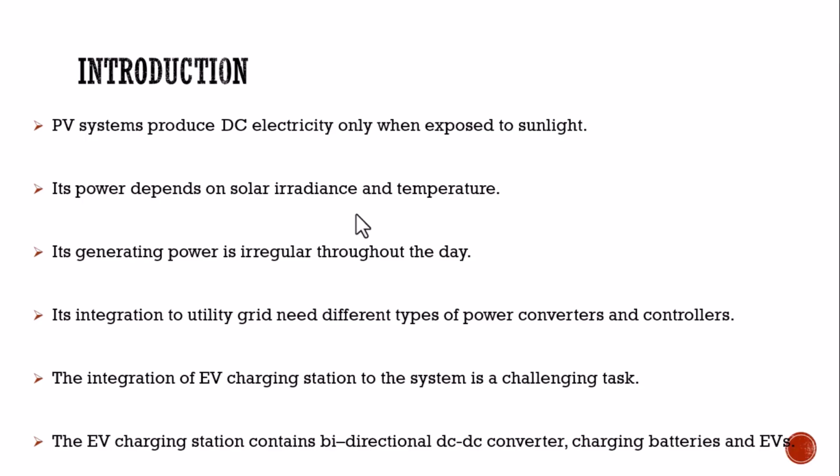Solar irradiance is the principal variable influencing the electrical output of a photovoltaic array. The power generated by a PV panel depends on incident irradiance, cell temperature, and module characteristics. As irradiance increases, current production rises, while temperature shifts primarily affect voltage output. Because these parameters fluctuate throughout the day, continuous power management is essential.